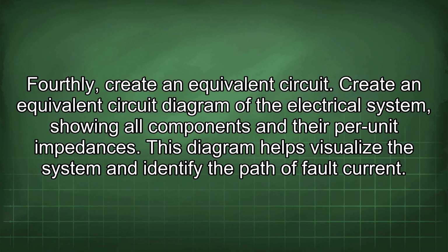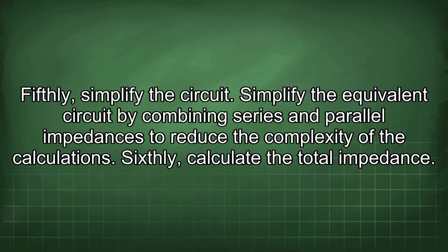Fourthly, create an equivalent circuit. Create an equivalent circuit diagram of the electrical system showing all components and their per unit impedances. This diagram helps visualize the system and identify the path of fault current. Fifthly, simplify the circuit. Simplify the equivalent circuit by combining series and parallel impedances to reduce the complexity of the calculations.